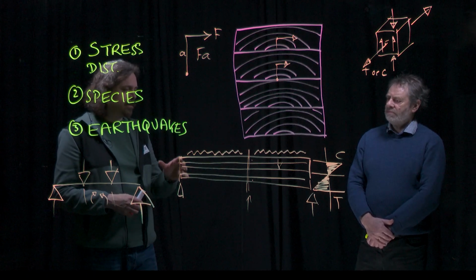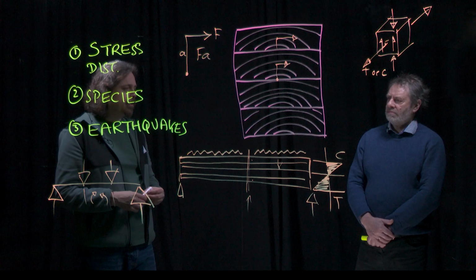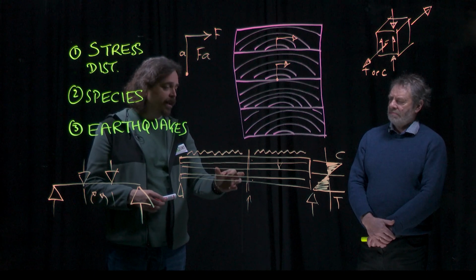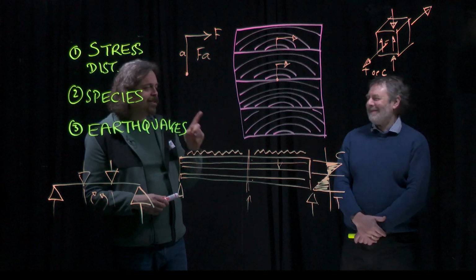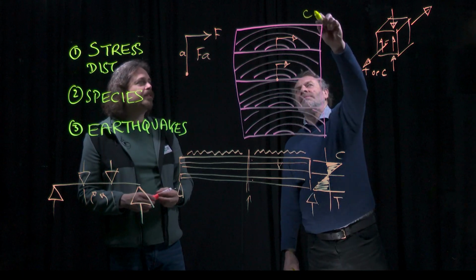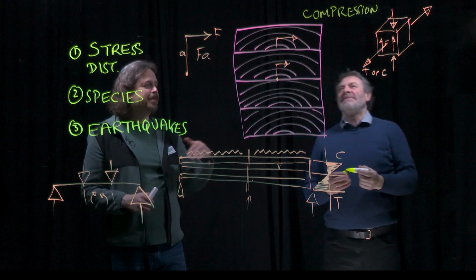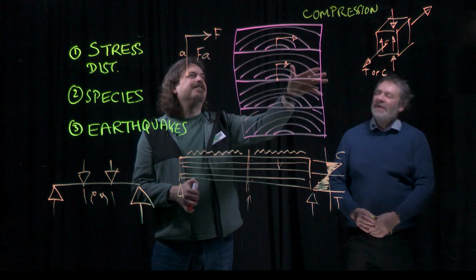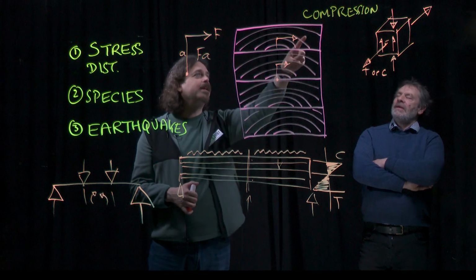For homogeneous glulam, where they're all the same grade, that's quite a simple process. But you are allowed to do something called combined glulam, where you can have different grades or strength classes in the different lamellas. Because the top and the bottom are more important in carrying the load. Compression, if it's bending that way. It's not always the case that the beam is sagging. Normally you have compression, but if the beam is hogging, you can have tension up there. But normally it's compression.